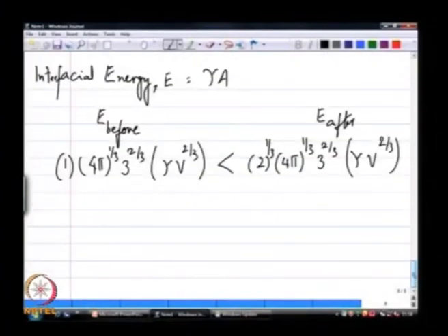That is how much interfacial energy I have to add. Gamma times that interfacial area is the amount of interfacial energy that I have to add. So, let us go back to looking at that for a moment with the numbers that we now know. We did this calculation before. Just to complete this thought here, this is for a single breakup event.